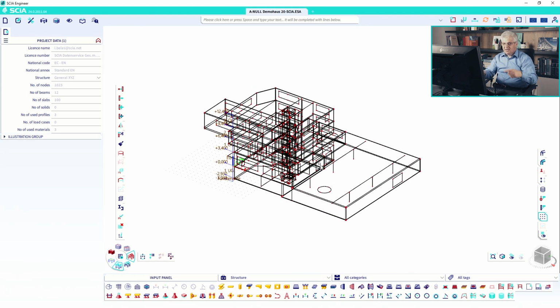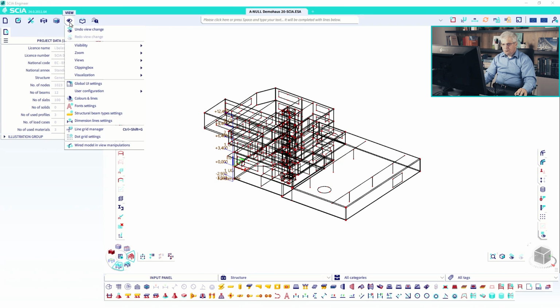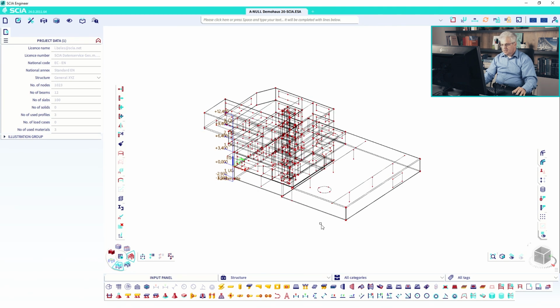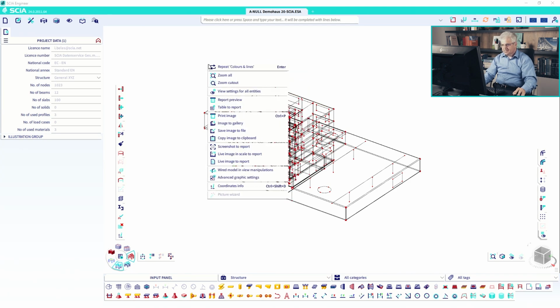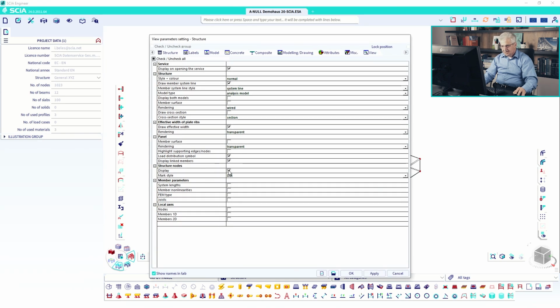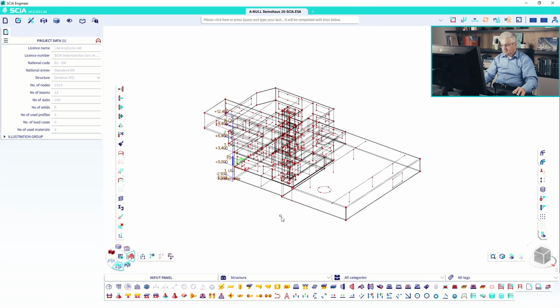So, and we can go back to our initial model. If you are doing this, then it's better to change the colors and use a very thin line, because these planes are not very thick and then you don't see the difference between the planes. You will also need the nodes. The nodes have to be activated, so you need the nodes. The structural nodes have to be also activated.